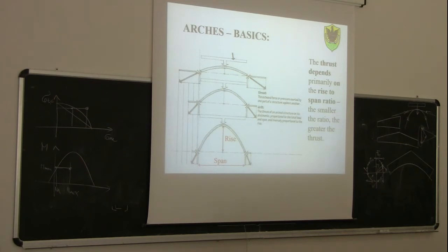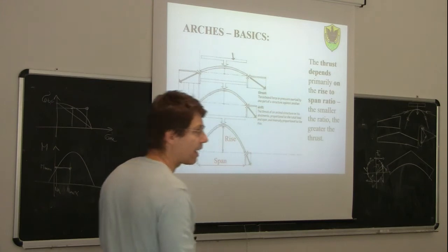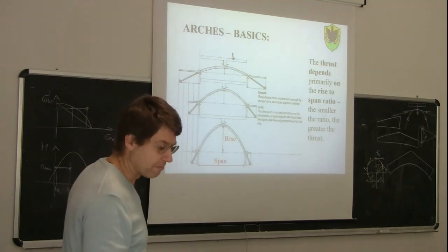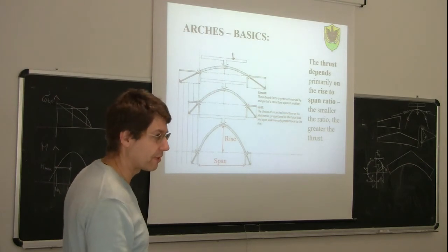bigger and bigger. So this is the reason why in an arch, if we want to reduce the actions within the arch, we need to increase the rise. So the higher the rise, the lower the compression force and the restraint reaction. Okay?